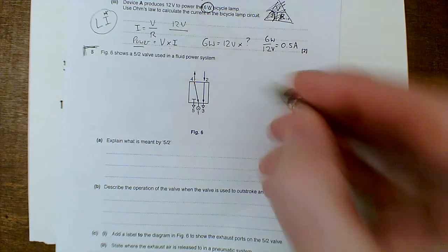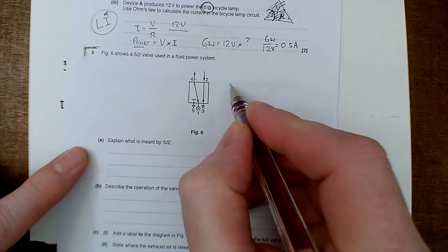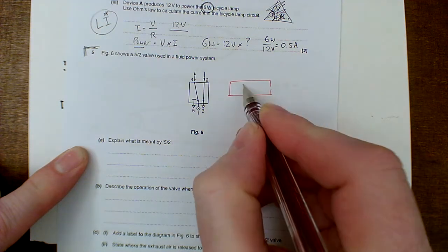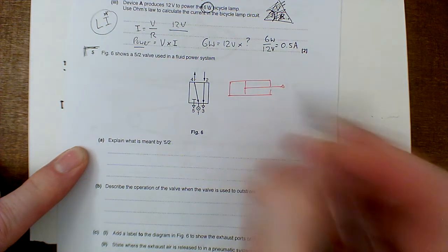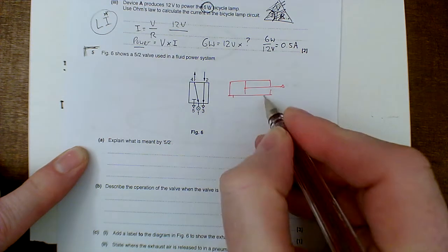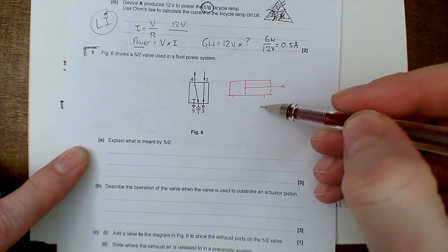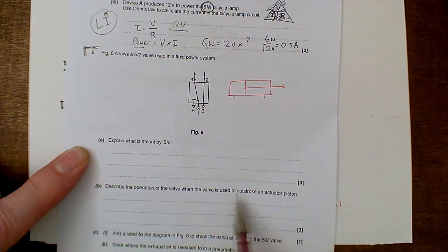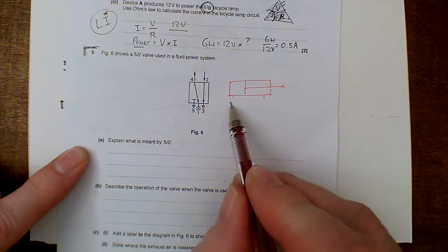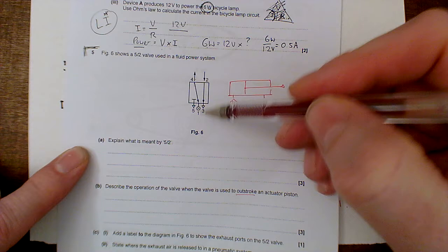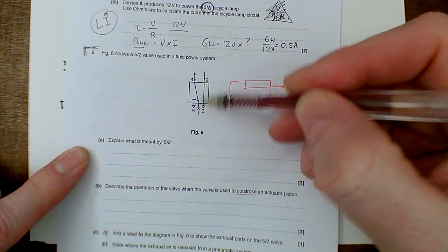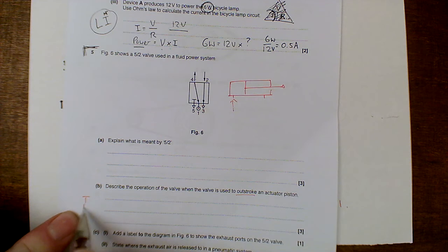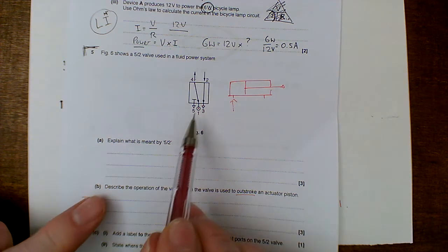So right now we've got the air coming from the back of the cylinder, and it's probably worth being able to sketch a cylinder. Quite simple, just like we've seen, and then put 2 ports on it. Well, I want the air to go in here to push it back, and if I want an outstroke, then I want the air coming in that one. Well, right now I've got that, I've got the air coming in here, it goes to port 4, so again, think like an engineer, talk like an engineer.